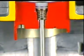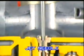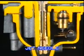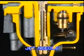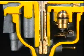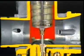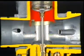The throttle valve is equipped with a tapered jet needle, which is positioned inside the needle jet. As the throttle valve moves up and down, the jet needle moves up and down with it.